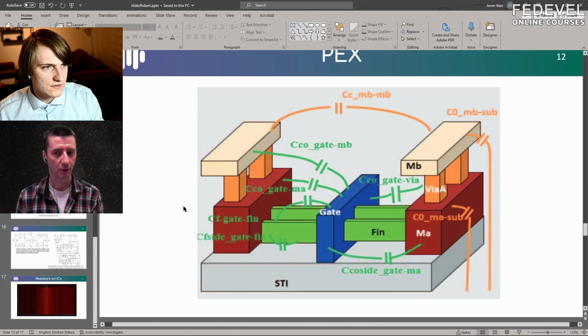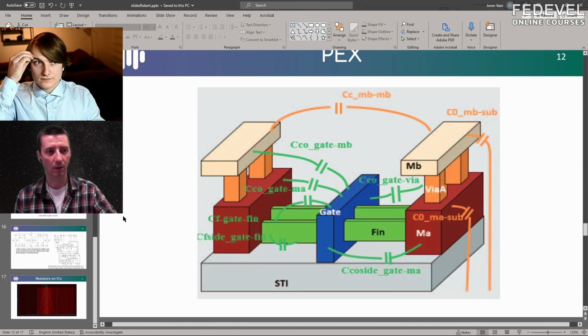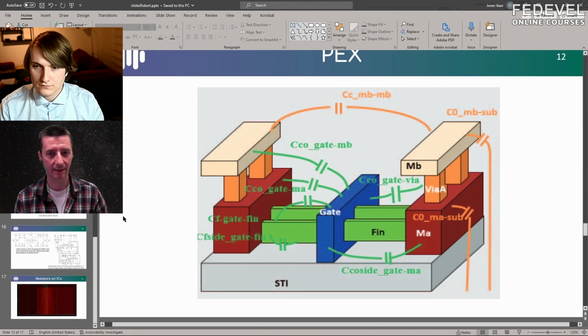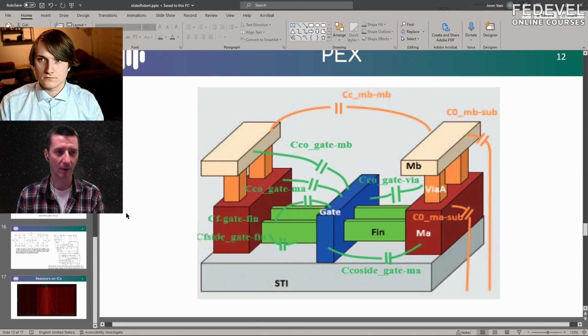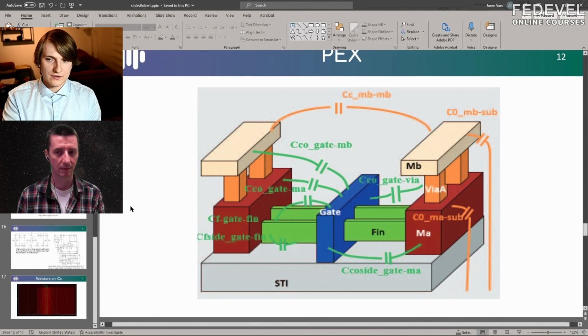So this is a 3D visualization of that. They are all these parasitic components. They are by default already included in the model. Just the values are calculated based on the specific design. So you have, for example, a transistor model that might include all of these parasitic capacitors up to metal 2 in the technology, and then above metal 2, another tool has to take over, and so outside of the transistor you have another tool which actually finds out where all these parasitics are. Okay, exactly.